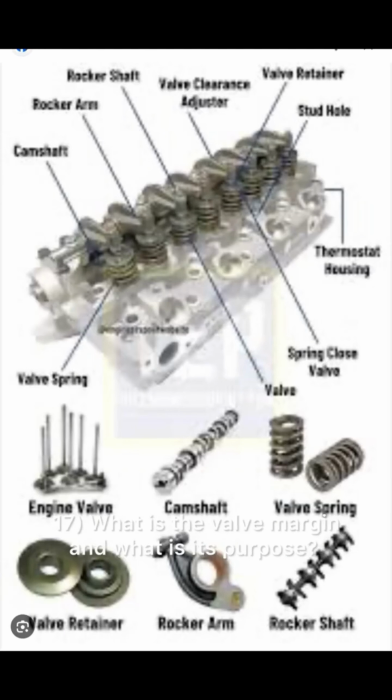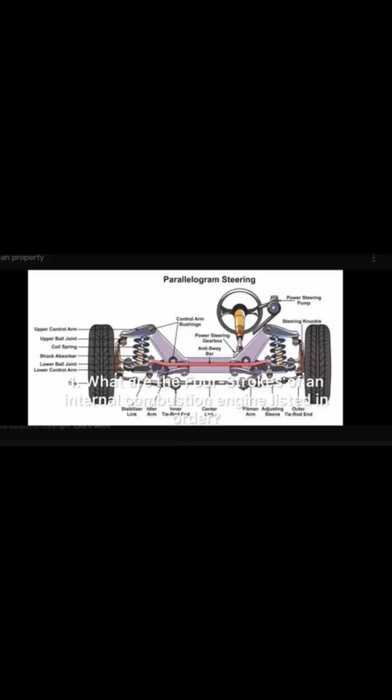17. What is the valve margin and what is its purpose? The material between the face and the head. The margin supports the valve face and provides material for heat absorption. 18. What is valve seat concentricity? Is the valve seat center line the same as the valve guide center line? 19. How can valves be bench tested for leaks? Vacuum check.